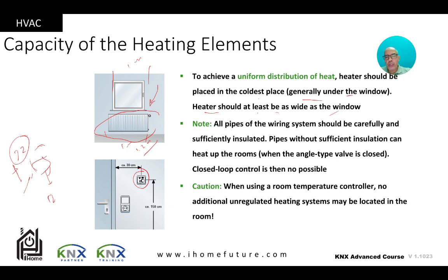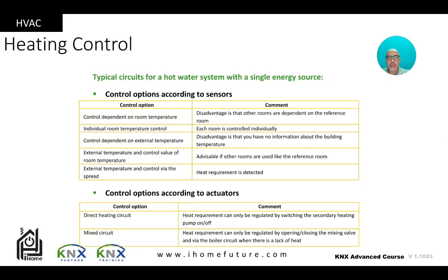So it's better to put it at this height, 150 centimeters, which is almost your height. You don't put it too low or too high. And put it 20 or 30 centimeters from the door, so it's not affected by opening and closing the door. You also shouldn't put anything else in the room affecting the temperature reading, like another room temperature controller.